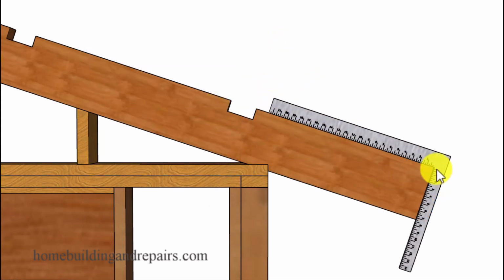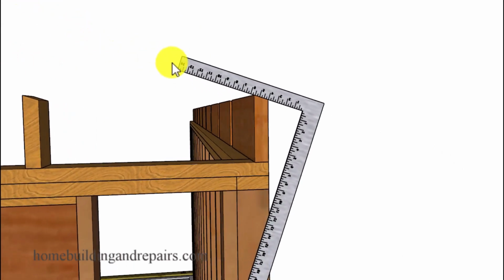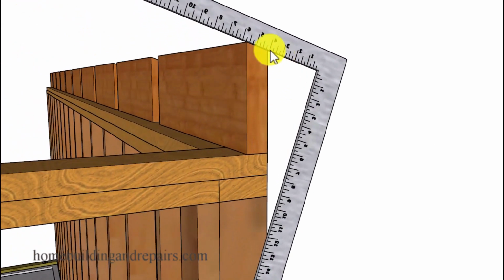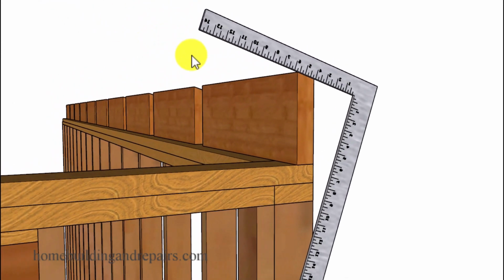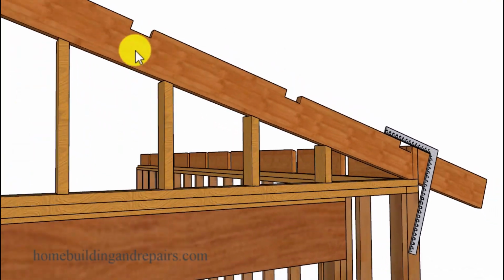And if we are going to have a square cut at the end, this one here is a little obvious. We can simply move the framing square to the end and mark the desired distance for the overhang with a 90-degree angle. And if you need the angle for the top of the blocks, then again, we're going to be able to use the framing square for that also. And since I can't think of any other angles you're going to need for your gable roof,